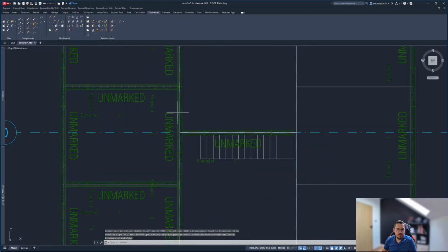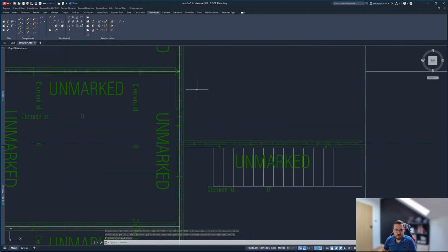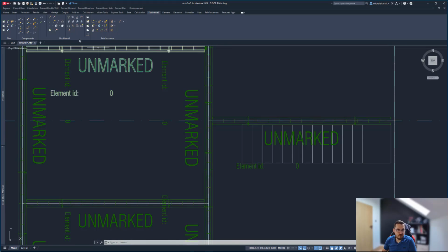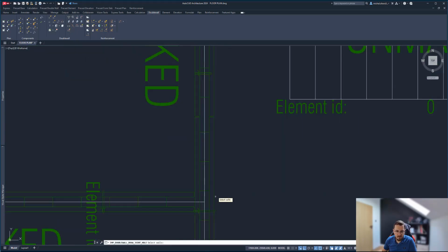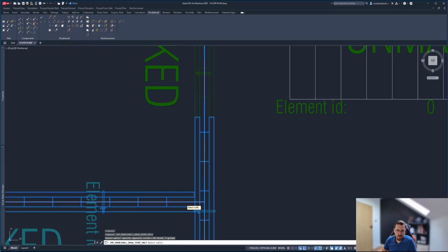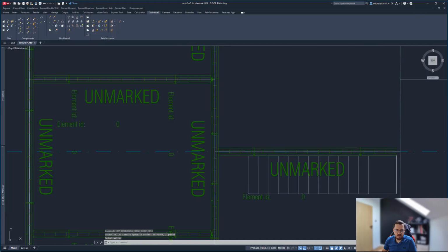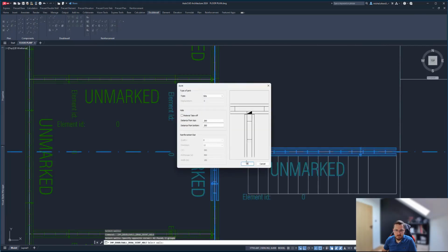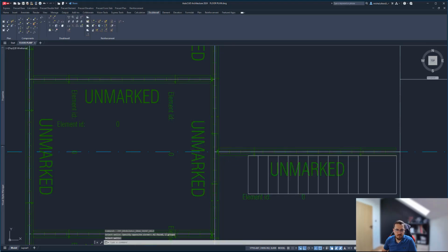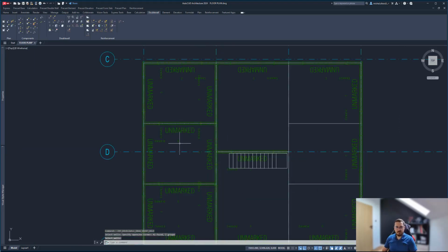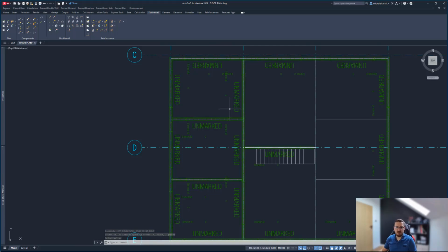That's perfect. And for that, simply put, let's do another T connection here very quickly. Just press space to accept that, and another one here that will allow me to get this connection going. Yep, that's done. As you can see, that's very fast, very quick.